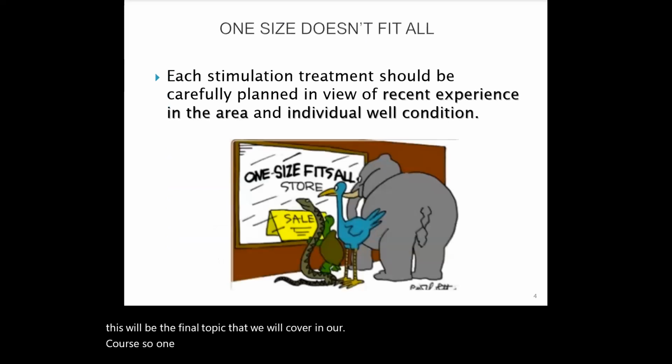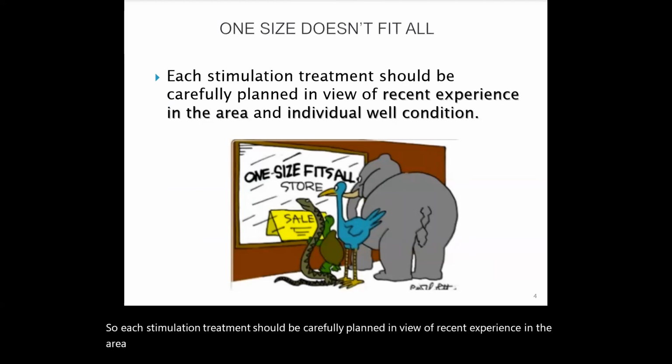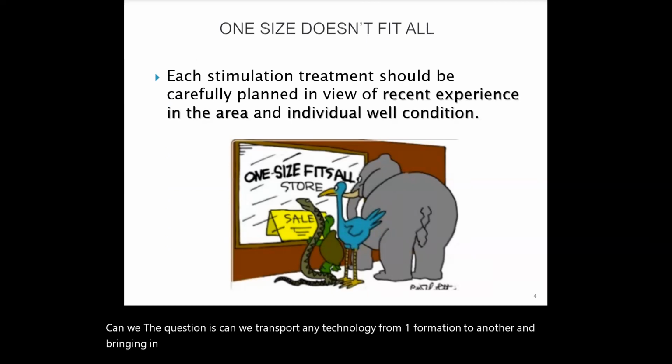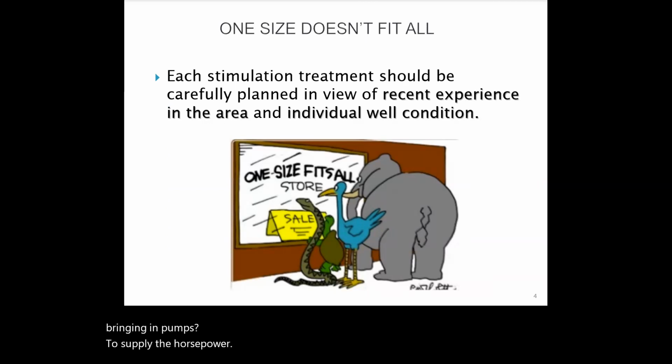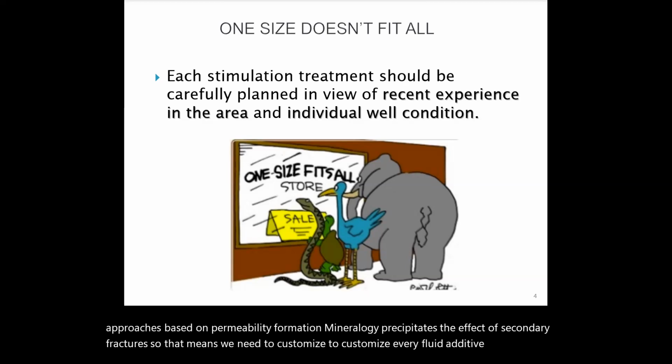So one thing that I wanted to emphasize here is that one size doesn't fit all. Each stimulation treatment should be carefully planned in view of recent experience in the area and individual well condition. The question is, can we transport any technology from one formation to another and bring in pumps to supply the horsepower? Simply no. Each and every one of these rocks and reservoirs is unique and requires a different approach based on permeability, formation mineralogy, precipitates, and the effect of secondary fractures. So we need to customize every fluid, additive, and design to get the most out of the reservoir